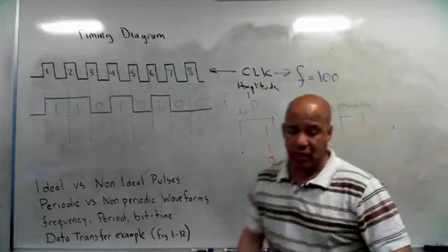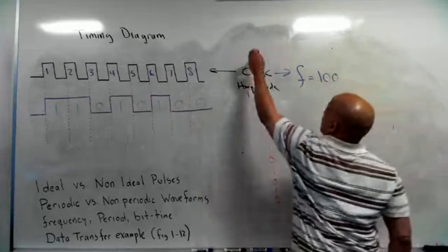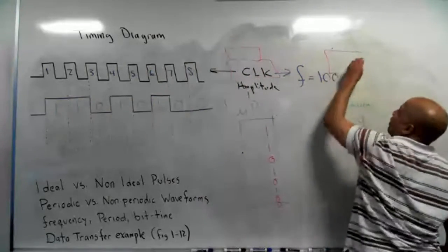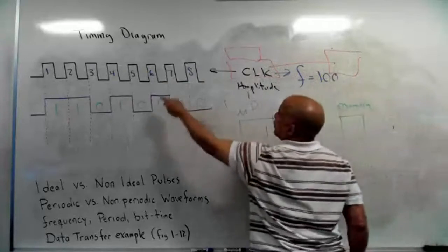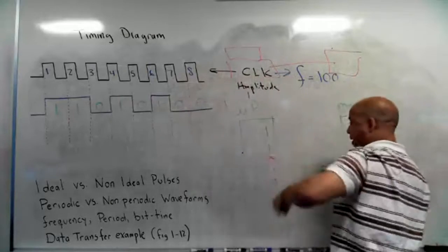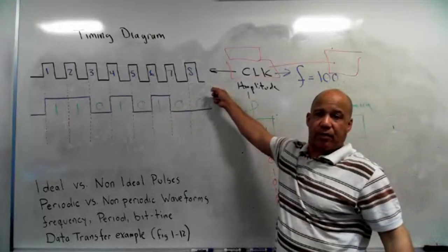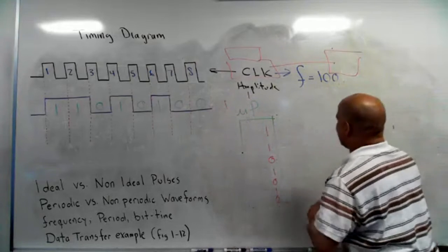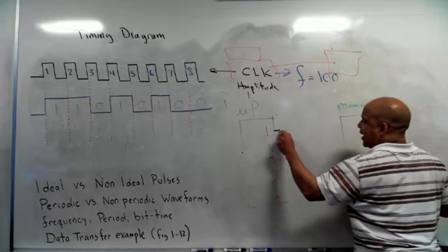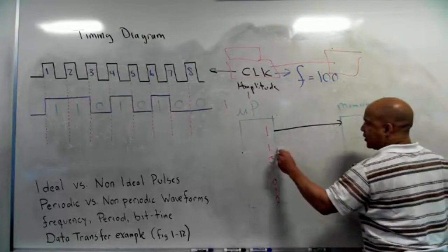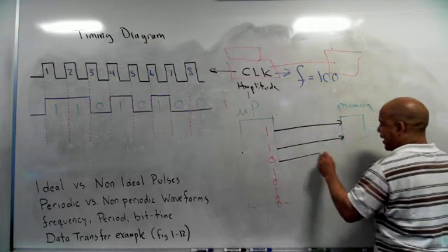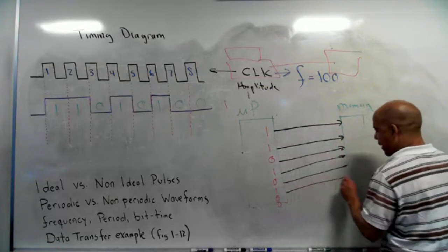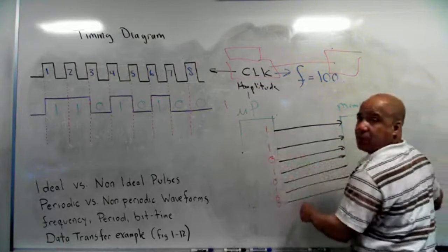Well, what I showed you in this diagram was I got the computer here, and I got the printer over here. I got one line, so these bits are sent bit by bit by bit, and that took 80 microseconds. Well, inside of your device, I actually have these lines connected. There's 8 of them. There's a line like this, like this. There's 8 lines in here. There's a line for each bit.